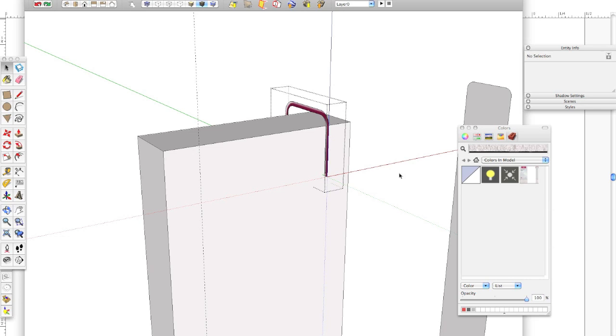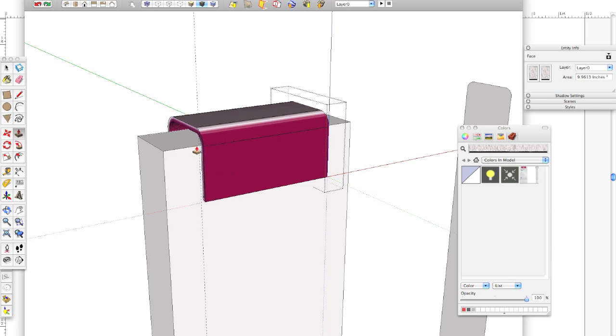It's going to enter me inside the group, and you'll notice it shades out any imagery outside of the model or the active group that you're in. But it does show the guide, which in our case is beneficial because now I can extrude this and I can infer to the guide for my exact positioning of that.